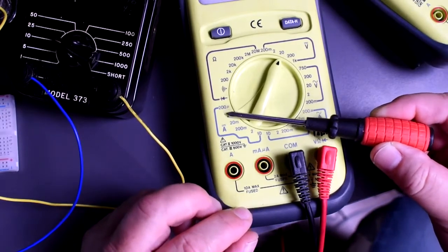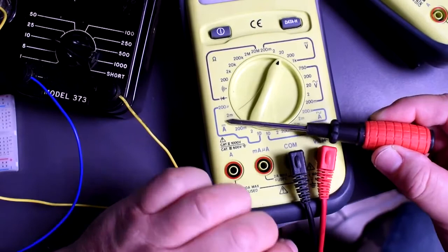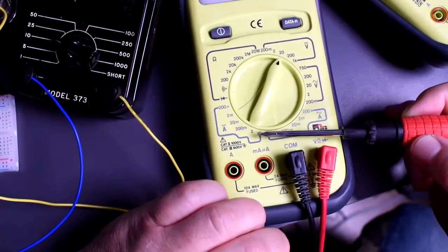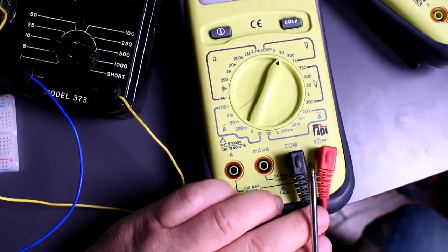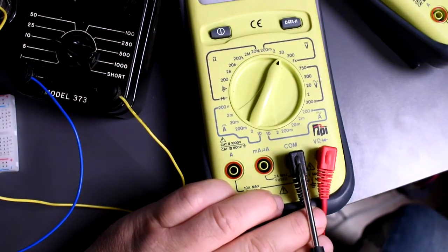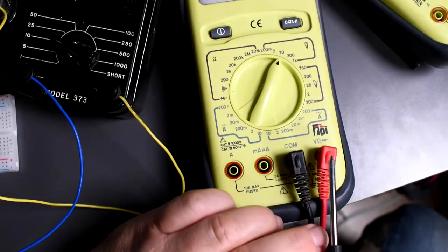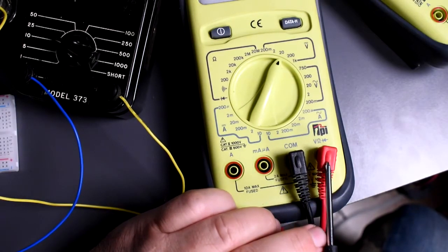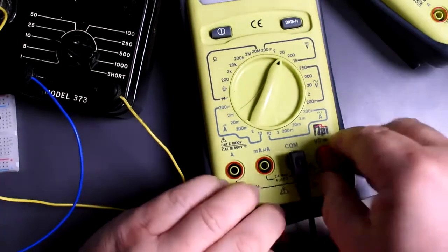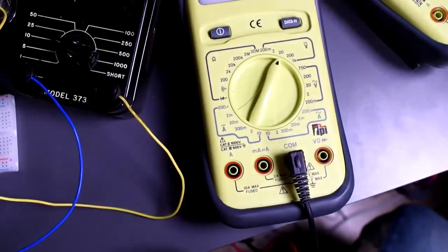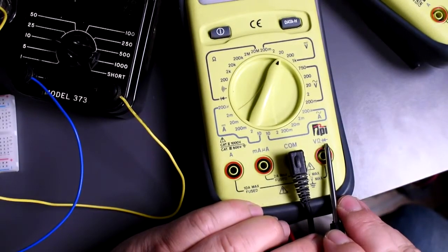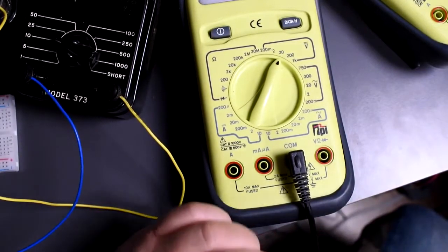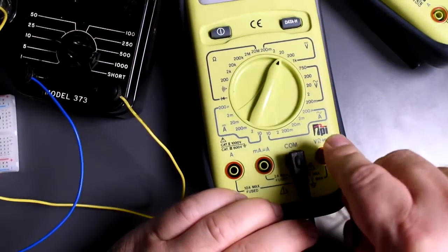That's a multimeter. It can do more than one function. So this is one of the functions. You can also measure current. Now let's take a look at the ports. As we said last time, the black lead goes to the common, and that's usually considered negative. If it's DC, then the red goes into whatever else is being measured. This port right here is marked as voltage, resistance, and diode tester. So if you want to measure voltage, you are going to use this port.